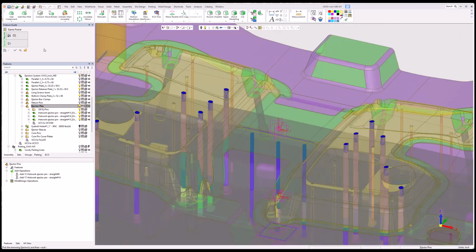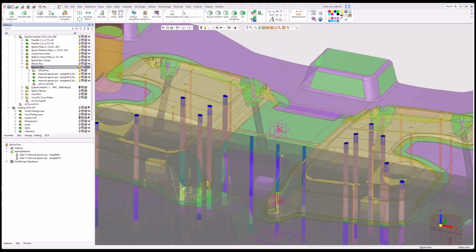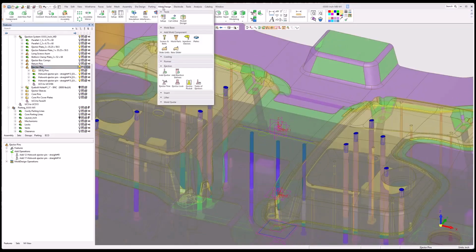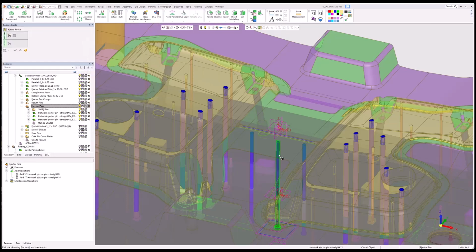Let's do this. Let's say after you wanted to make this a Z pin, I could add my ejector lock to it first, and then I would do the pocketing. Okay. I'll go right to the pocketing here. I'm going to pick this one because the height's different. And again, I want at least 1 inch of ream, but I have to take into consideration how much below I cut that pin. I can say apply.